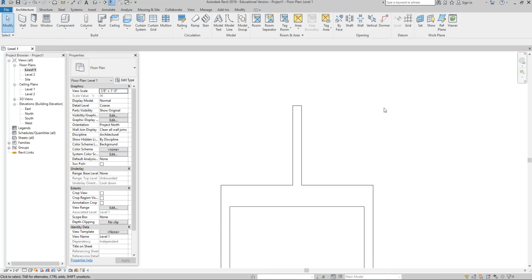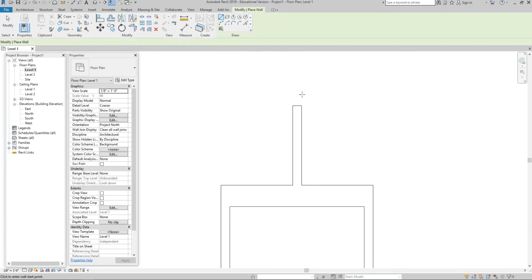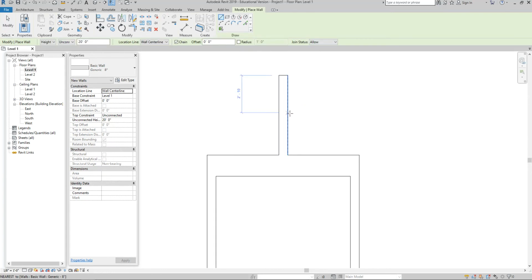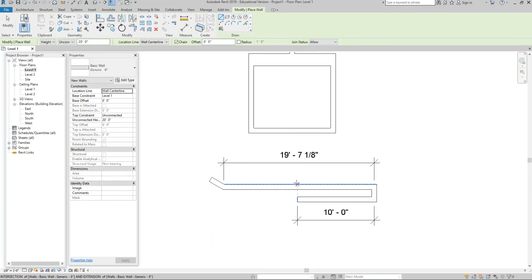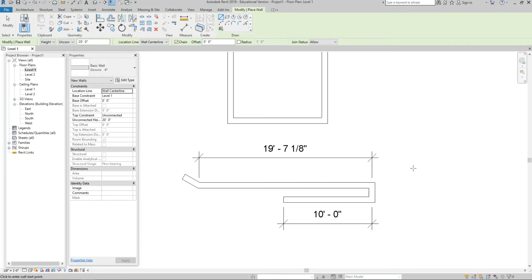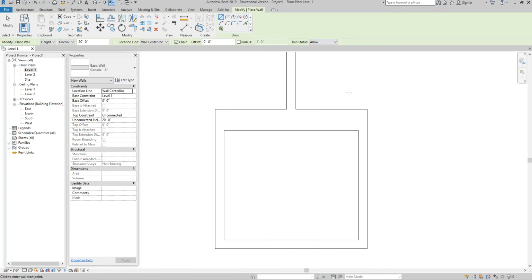It will let you choose specific points on other geometry to draw from. So the most common ones, let me show you. We have midpoint, right? Midpoint of that line. Now because this wall is, oh no, it didn't do the midpoint there. It's not broken, never mind. We have a midpoint there, we have a midpoint there, we have a midpoint there, right? So Revit will calculate the midpoint on really any object, any shape, okay? The pink triangle is a midpoint.